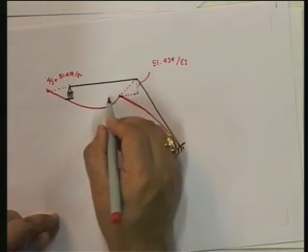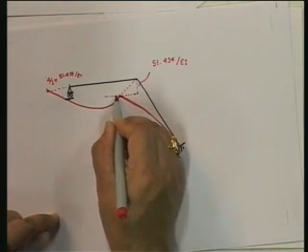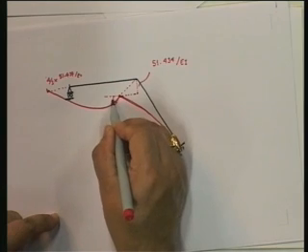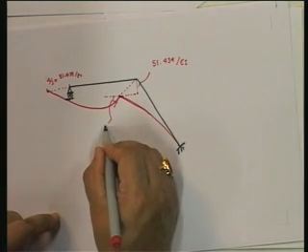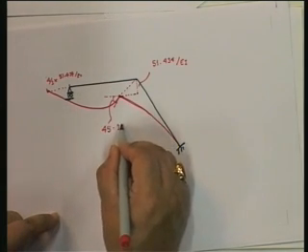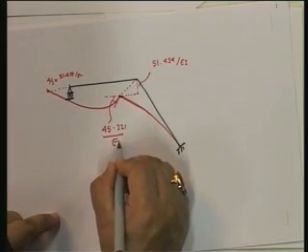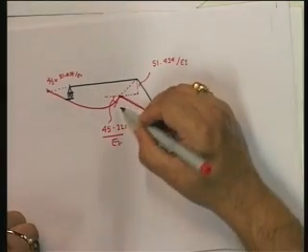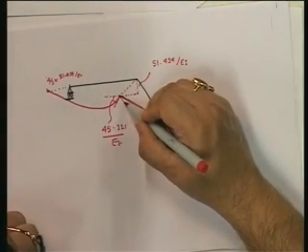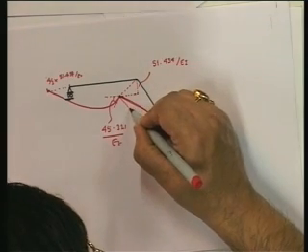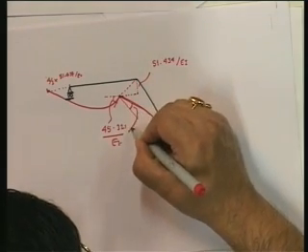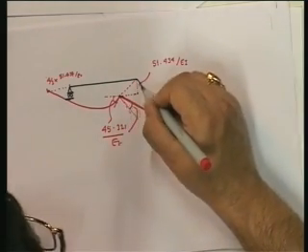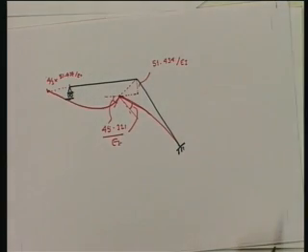So this rotation from the horizontal is equal to 45.321 upon EI. And if you were to look at it from this, this is also equal to this from the original. Okay, this gives you the displaced shape of the structure.